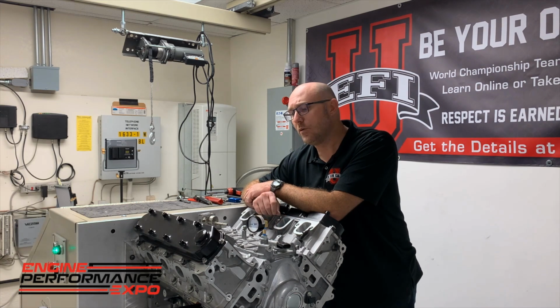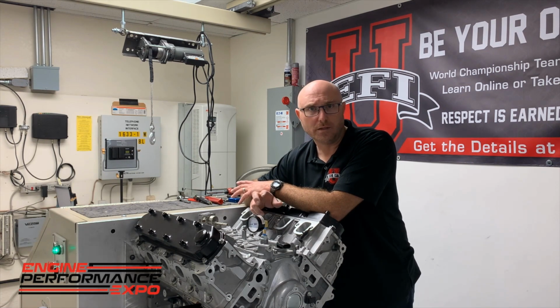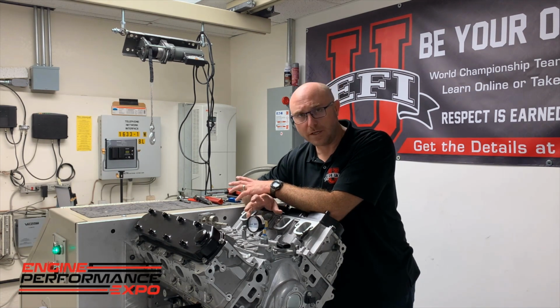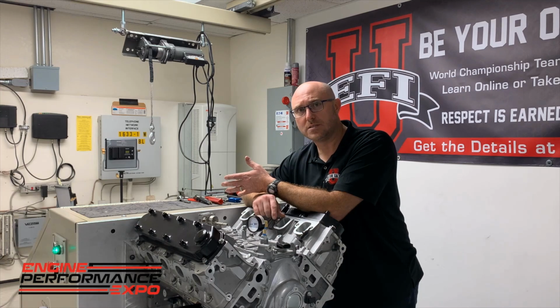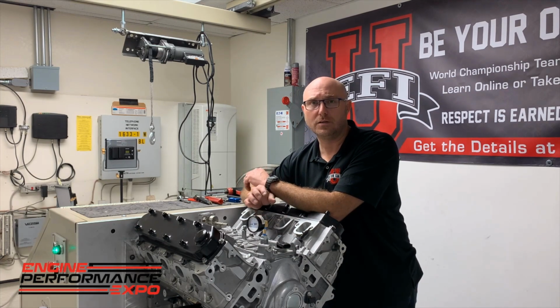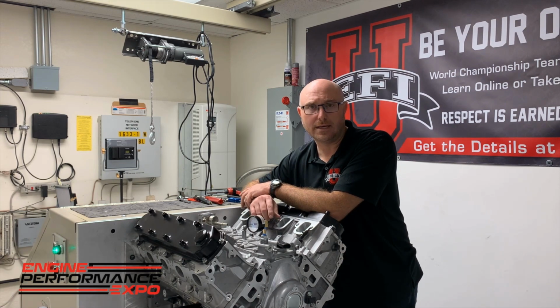And so it's not always just about finding limit speed or always just to find dynamic stability. It could be, for example, about durability. Maybe I have a system that I know is pretty good, and I want to make sure that it will go all the way till the end of the race. We can set up the test sequence to look just like the racetrack. We can include gear changes, throttle blips, just like you're looking at the data log in the car.